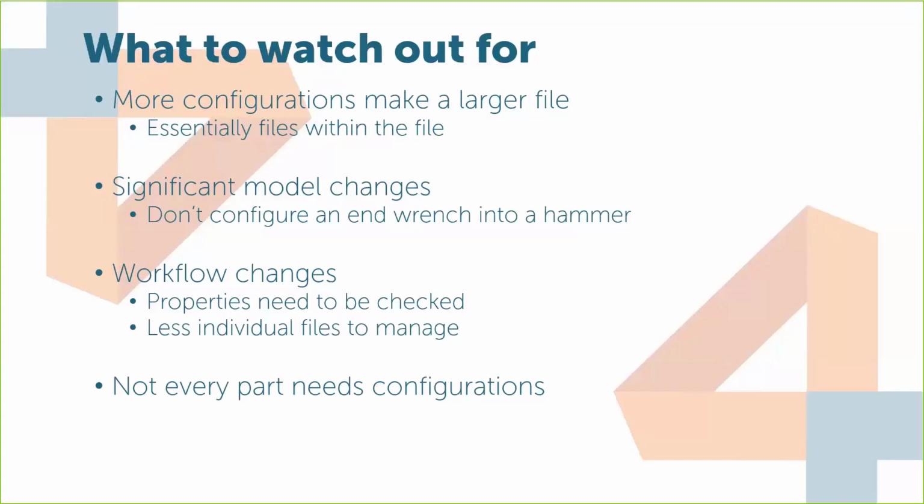If you use SOLIDWORKS file properties, you need to be aware of configuration-specific file properties, because each configuration can have its own properties that will override the overall part configuration. I know that's a lot to say right there, but again, with trying to get a lot of power out of configurations, there's a few things one needs to think about.